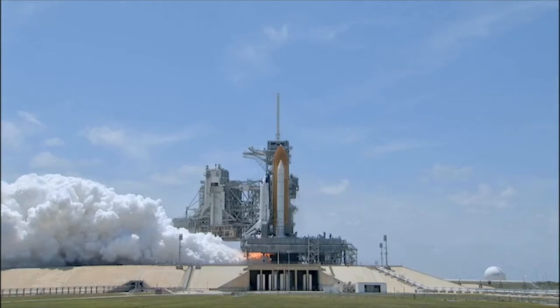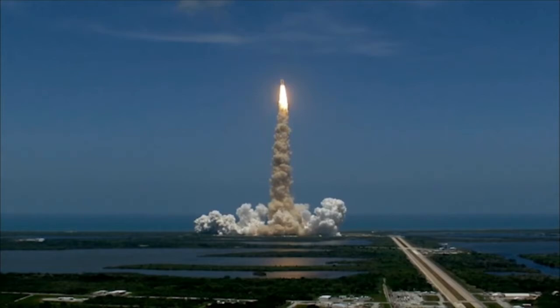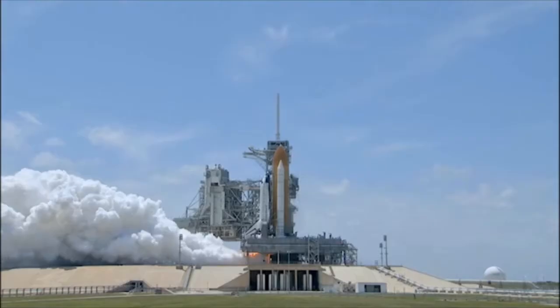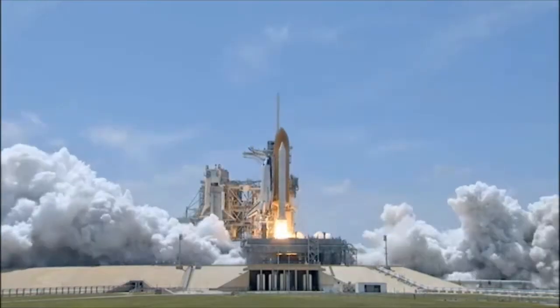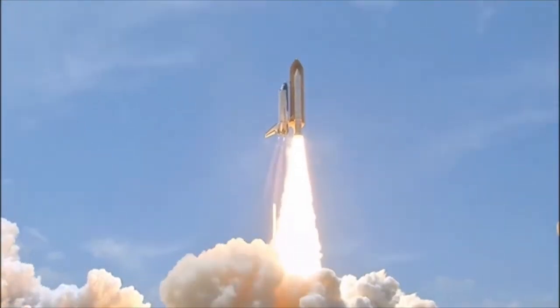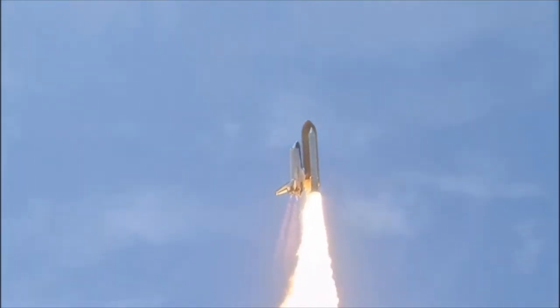If we just looked at the rocket when it initially launched, the mass of the rocket is the dry mass of the rocket plus all the fuel in there. It's at rest. In a state much later on, the mass of the rocket has decreased and the speed has increased, but we can't just compare this initial to this final state, because throughout this process there was a continuous mass transfer. Fuel was ejected backwards. So how do we analyze these types of continuous mass transfer problems?